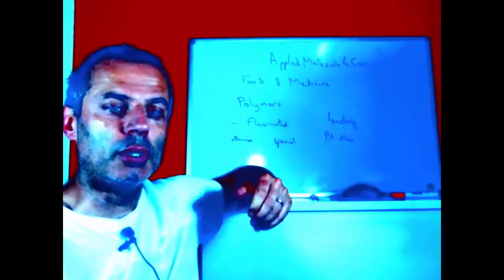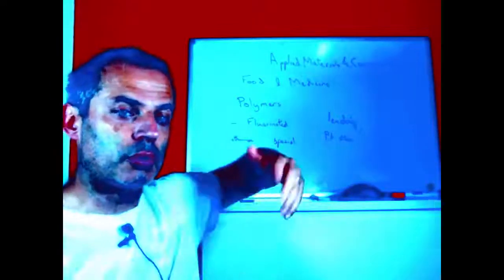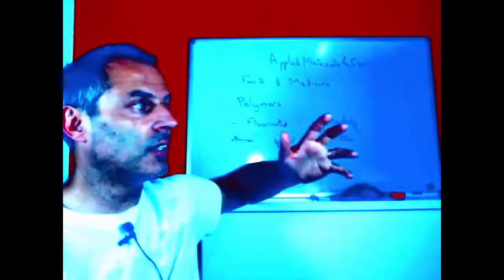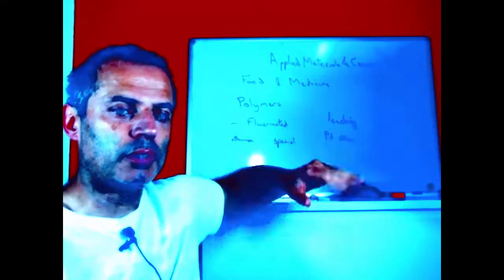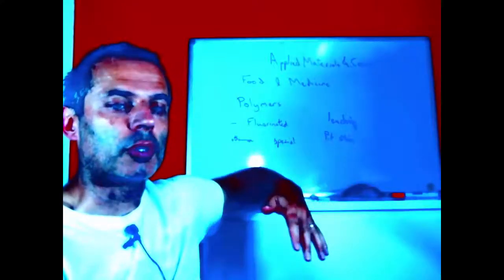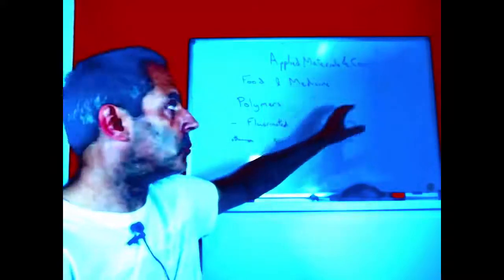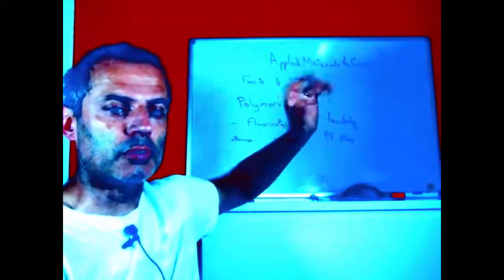This is particularly common in epoxy adhesives, where the reaction generates a stiff, hard matrix, which means that it's very hard for the small monomers to then get to each other to form polymer. And so typically there's a little bit of short chain material left, and that migrates to the interfaces. So it migrates to the interface to the other side, but it also migrates to the outside interface, and that can leach into the water, which is why epoxies are seldom considered to be food safe. There are some that are food safe, but not very many.